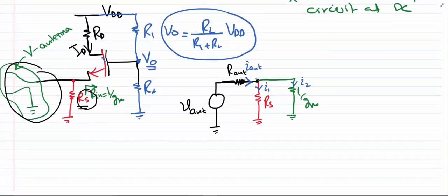So now here we see that some part of the antenna current, which is coming from the valuable signal, passes through the resistance Rs, which we have used for the bias current to flow. Now that current I1 is an undesired part because we want the complete current from the antenna to pass through the Mosfet.